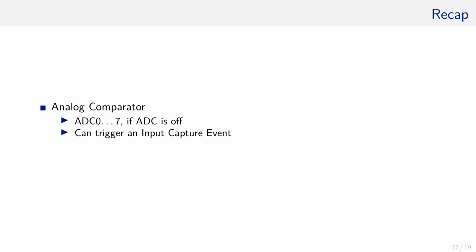Well, you might ask, what is the purpose of the comparator after all? It can do much less than an ADC. That is true, but many times engineering is about simplicity. Imagine an example. You would like to know if the air temperature is 25 degrees Celsius or higher. Using the ADC, you first have to calibrate the internal temperature sensor. Then you have to keep sampling it from time to time to check the temperature.